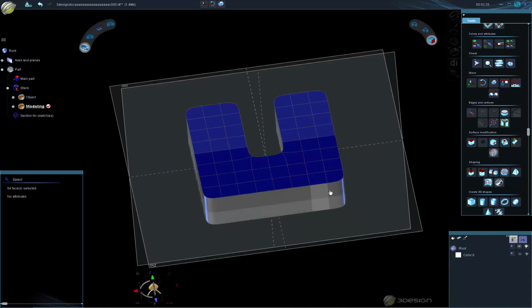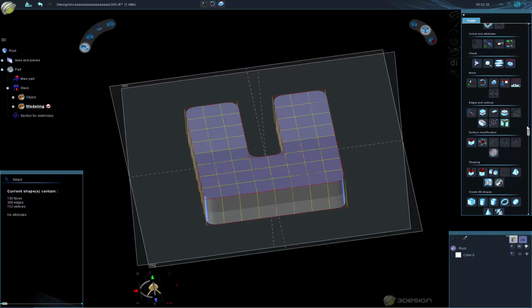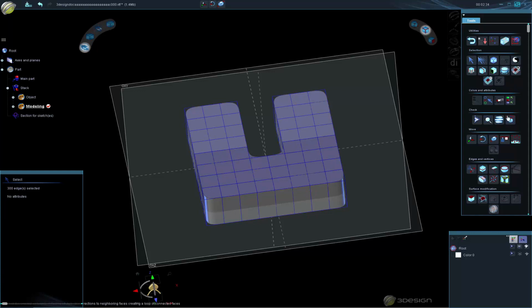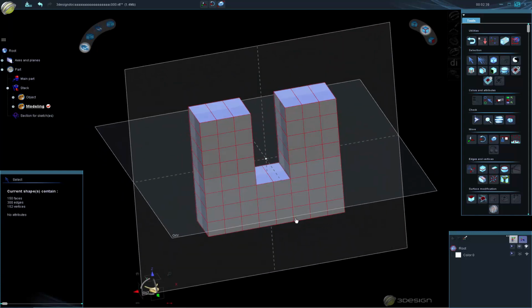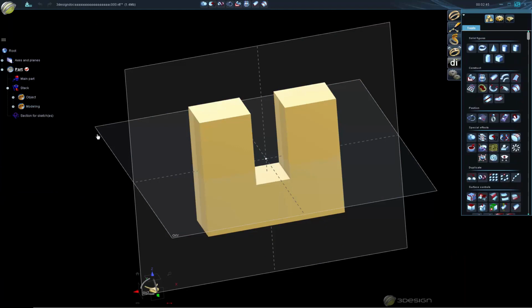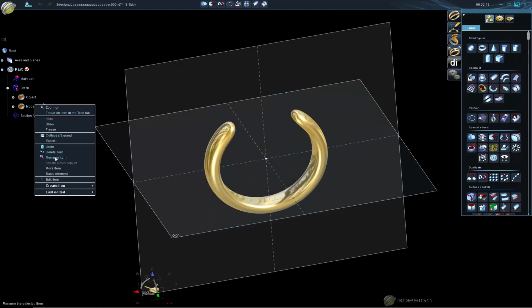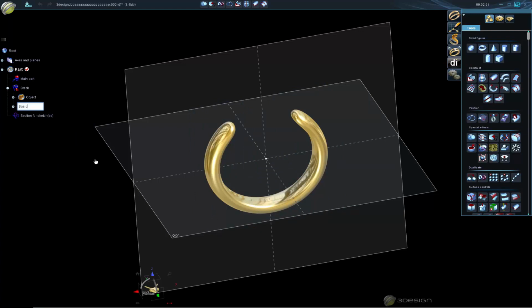And I'm just going to shell it so that it's on the other side of my band. So it's fully encompassed. And then there's one more step that's helpful, very important, is to select all the edges and sharpen them. So we get a nice boxy mesh, keeping our envelope mesh as simple as possible. So we're going to exit out of 3Shaper again. And I'm going to hide and rename this mesh as my basic envelope.